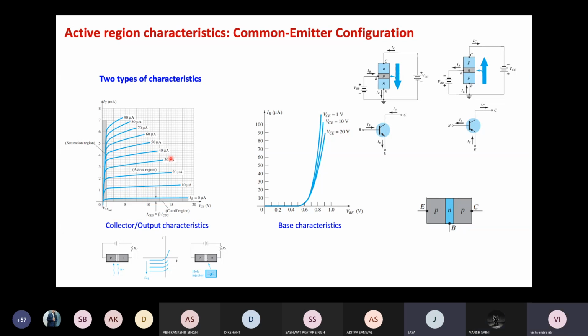Okay, so this is how the reverse bias characteristics look like, if you recall them. And these are the IV characteristics for different lighting conditions. These were the characteristics in the case of a solar cell. In this third quadrant, the minority carriers were more in the case of the solar cell because of the light.